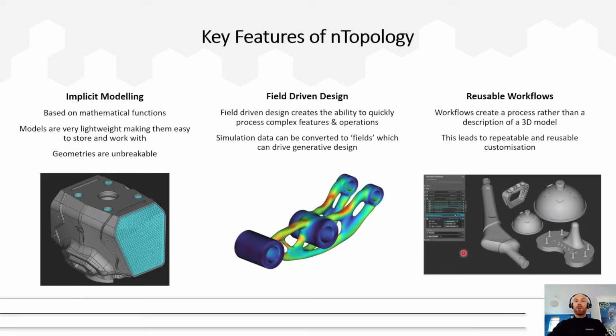So in the screen recording below, we can see some patient-specific CAD data. This has been brought into nTopology, and we're applying a stochastic lattice to the faces of these pieces of CAD data. You can see the models in nTopology are so robust that we can just click on a face, click on a model, and it's going to apply that stochastic lattice to whichever face we tell nTopology to apply it to.